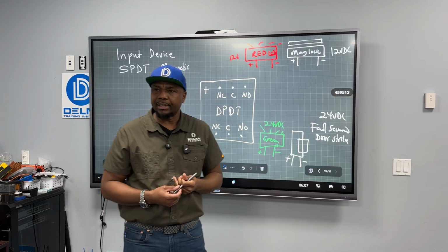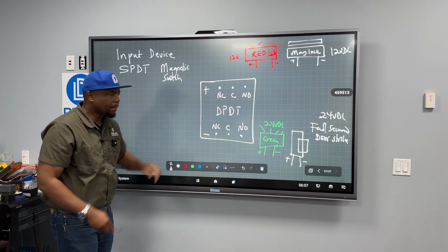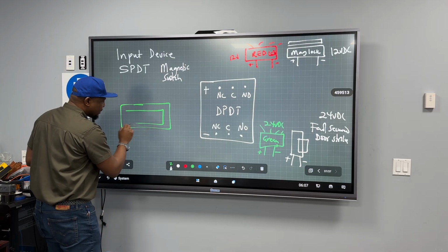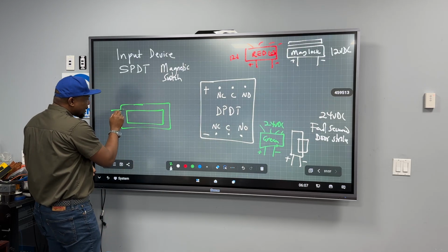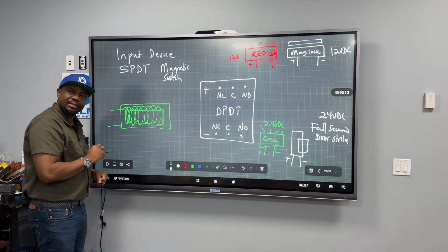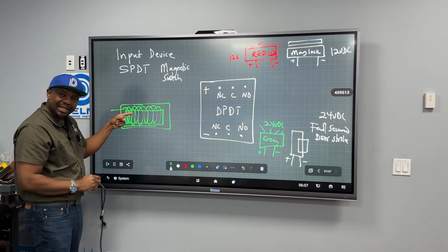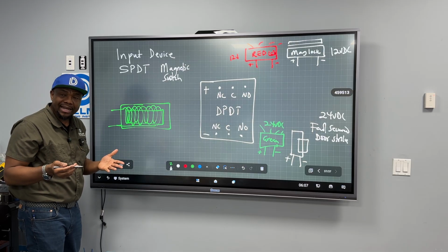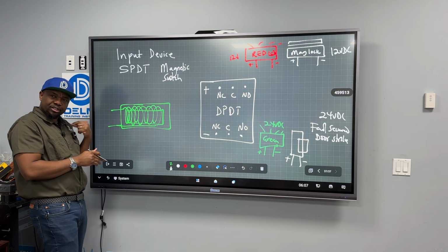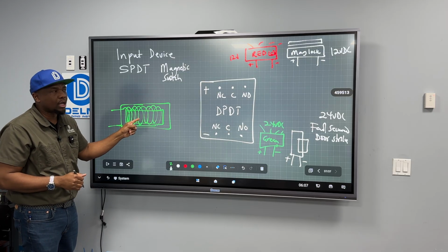How does a Maglock work? The Maglock works exactly the same as what I was telling you happens on the coil. So inside the magnetic lock, it has a piece of metal like this, and that has a coil built around it, like that. And that coil comes back here. So when you send electricity around the soft iron, it creates a temporary magnet. And when you bring the plate next to it, it attracts it. When you take away the electricity, it's no longer a magnet. So this is just the principle under which a magnetic lock works.